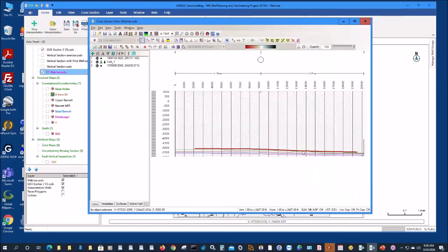Okay, and notice it's a pretty straightforward setup here. There's my little stub well number 2 way up here. It's got a TD of 100 feet, which is typically what you want to do when you're using our well planning tool: create a little stub well and then pick your target points in the cross section in the geomodel, right? And it generates a proposed directional survey, etc., that you could feed to your drilling group.